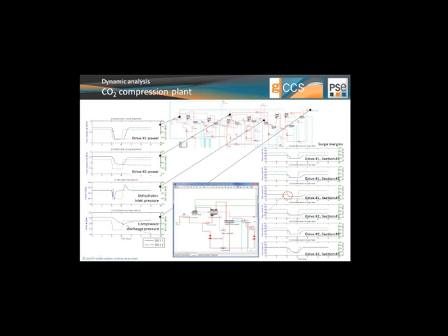On the other hand, we can see that all sections, both on the fixed speed side and on the variable speed side, would go into surge, obviously at different points. The last one to go into surge being section 3 here, connected to the second driver. And obviously all the valves in this simulation are switching to being controlled, and all the recycle loops would open so as to avoid the compressor sections going into full surge and maintaining a level of about 10% of the surge margin.